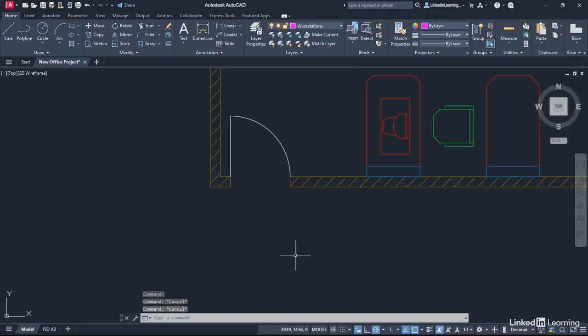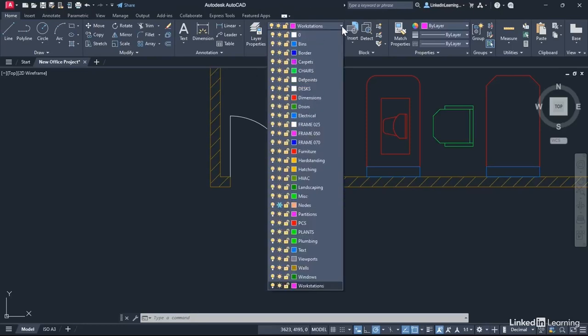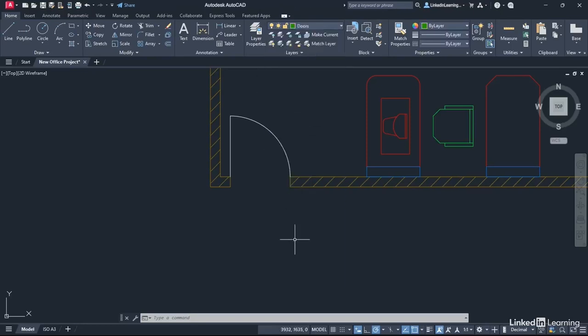Now you'll remember when we created the blocks previously, if we put the objects that make up the block on the 0 layer and change the current drafting layer, when you bring the block in, it'll automatically go onto that current drafting layer. So let's change our current drafting layer to doors now as well. Okay, now a dynamic block kind of follows along with creating a regular block.